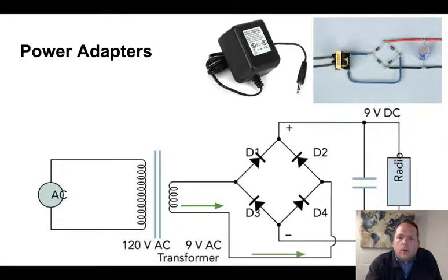Going to go down here, cross the bridge, and get up to the diode network. And again, it could flow through diode 2, or diode 4, but diode 4 is flipped around, so it is an insulator path for the current. In that context, nothing can go through D4 from this direction, so the current's all going to flow through D2. And notice it gets to that point where it got when current was flowing in the other direction. So this 4-diode network is actually what reverses the direction of the current half of the time, so that all the current coming out of it is always in the same direction.